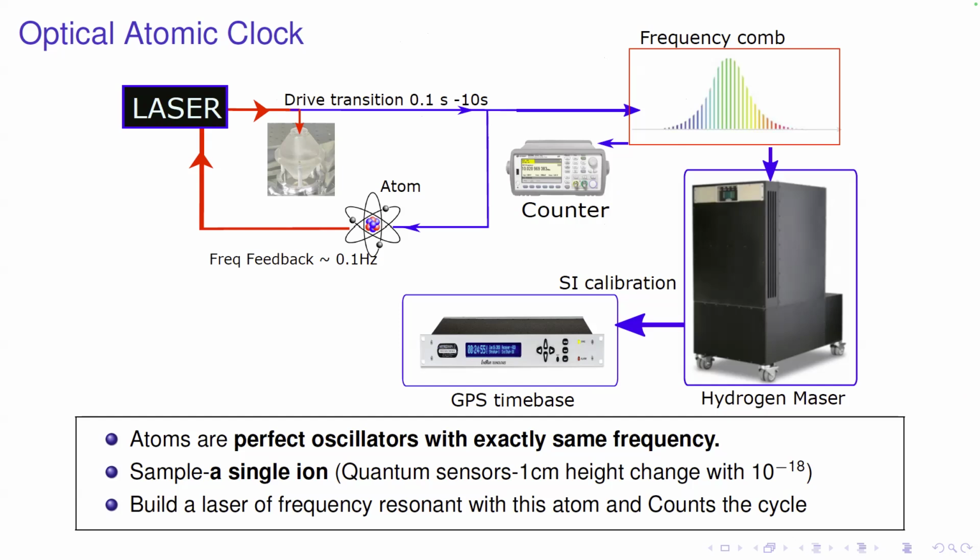And since this is very high, we don't have well-developed technologies to read out this frequency. So what do we have? We have telecom frequency readout, right, which is in the megahertz or gigahertz. Our Wi-Fi is in the gigahertz. So we have the technology to read out gigahertz frequency, but we don't have good technology to read out terahertz frequency. So we have to down-convert the terahertz frequency to megahertz or gigahertz frequency, which is done with a frequency comb.